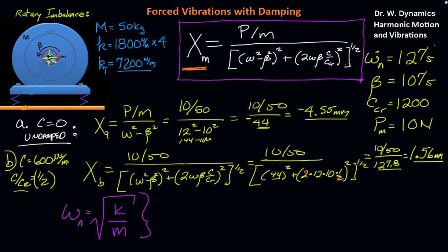In fact, if we look at this equation, we'd ideally like omega to increase. So we could do that by increasing k or decreasing m. And looking at this motor, I don't think we could decrease the weight of it easily. However, if we had to, we could replace the springs. Let's say we go out and we get springs that have 2,500 newtons per meter times 4.